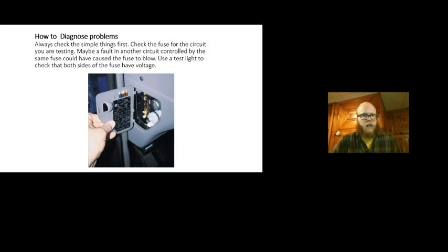Now, we've talked a lot about fuses and a lot about fuses popping, and when you have an issue, the first thing a lot of people will check is the fuse, because it's pretty easy to get to, and there's lots of good information usually to help you figure out what fuse it is that you need to look at. But if we have a popped fuse, that is not an opportunity to be like, oh good, I can just put a fuse in this and it'll be fixed and everything's good and hooray. Something has gone wrong to cause that fuse to pop.